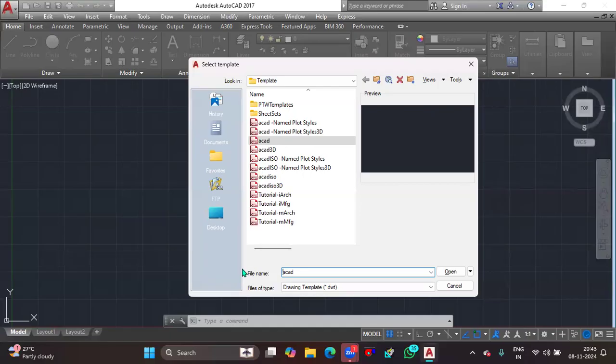So similarly, these templates also possess some kind of file extension, and the file type is .dwt, which is drawing template. But once you save this worked drawing, which is this template, then the saved file document should not be termed DWT. Instead of that, it should be saved as .dwg, which is the file extension for a saved AutoCAD file. All right. So let's start the work, guys.